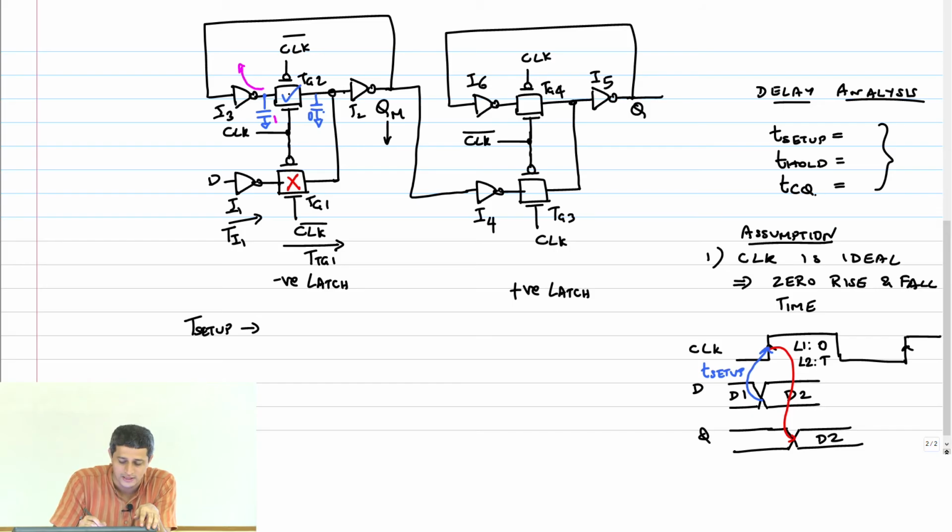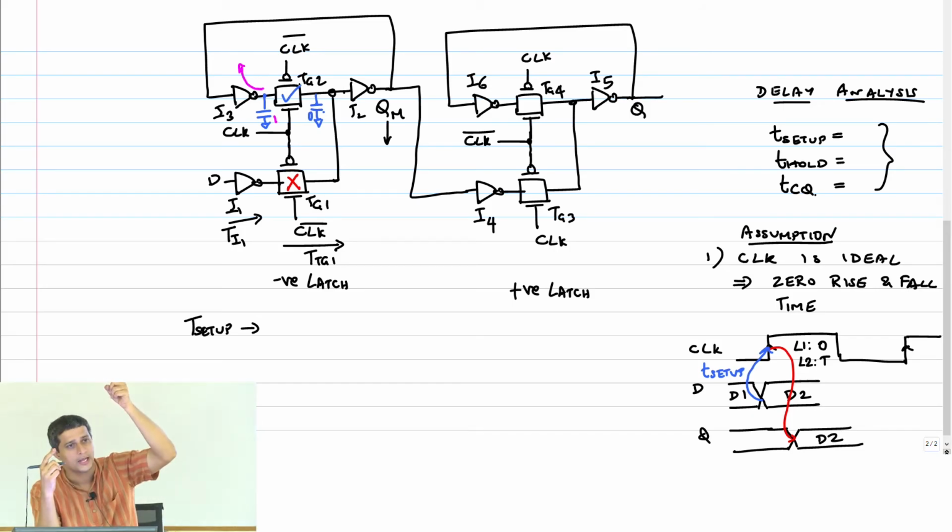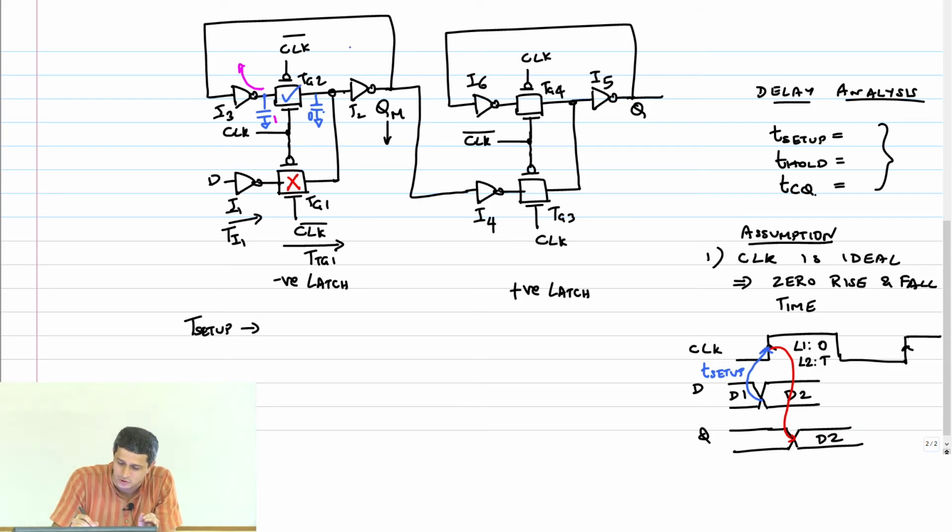It's a capacitor that's floating at ground. That means when this transmission gate TG2 turns on, and that has a logic 1 up there, it is going to charge this capacitor up now. So this capacitor will start rising slowly. And instead of storing 0 or 1, it may come to some in-between value depending on where this node voltage X eventually settles. If X is below the trip point of I2, then it will end up being a 0. If it's above the trip point, it will end up being a 1. So there is a sense of randomness there, which we don't want.